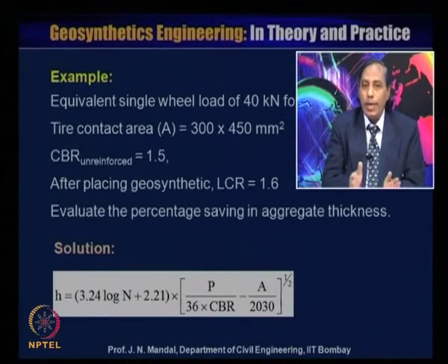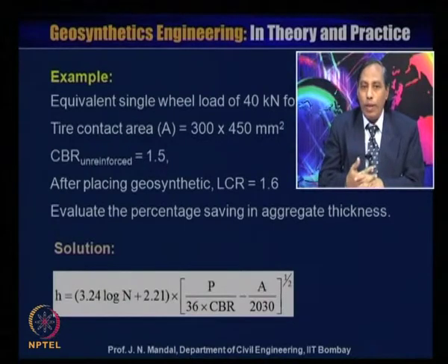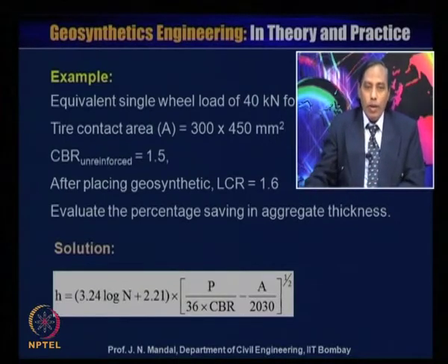So from that design chart also you can calculate the LCR value for a particular geogrid material. So evaluate the percentage of saving in aggregate thickness. Now you know this equation for the determination of the aggregate thickness.